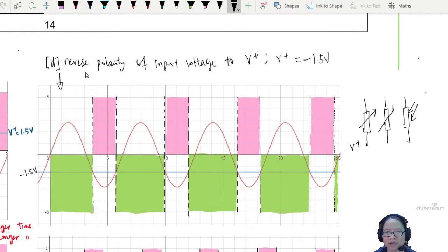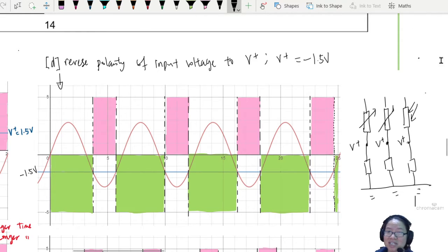So all these you connect to V plus. These are all your V plus connection. And then here you connect to another resistor. Doesn't matter. And then you ground it. So based on this potential divider, you can use different kinds of sensing device. You can even put a strain gauge there or piezoelectric transducer. How do you think the pedestrian crossing one works? Maybe someone presses it and then it will trigger some motion detection. Don't know. Every circuit is different. But here you can see this V plus, the possibilities are endless. You can change it any way you want.